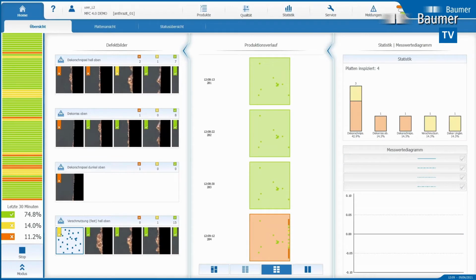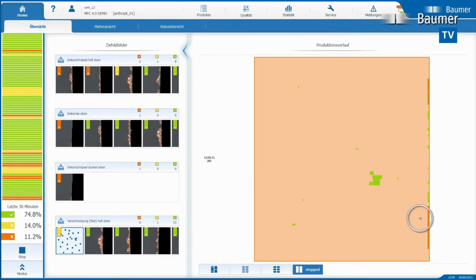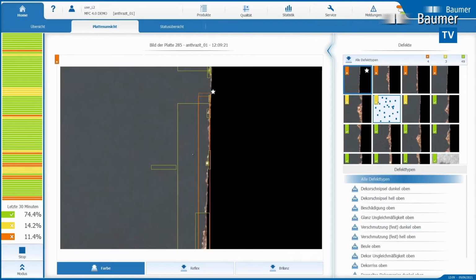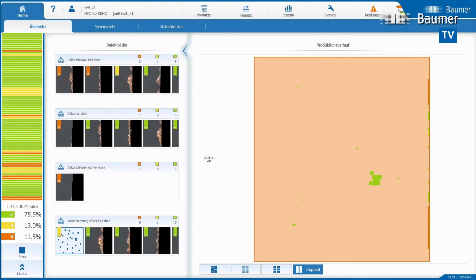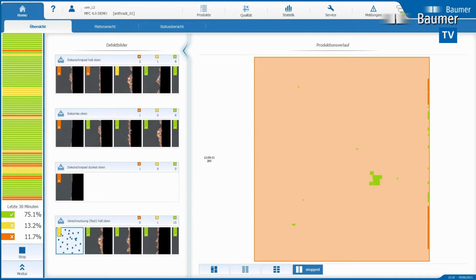The inspection system alerts non-tolerable defects. If the edge scraper does not work correctly, for example, the edges are not trimmed cleanly and the system reports edge defects. Until someone can take care of the defect source, edge scraper, I temporarily work with a slightly larger panel edge setting if the edge defects are still within the cutting tolerance. Now no panels are thrown away unnecessarily and I can take care of the edge scraper.